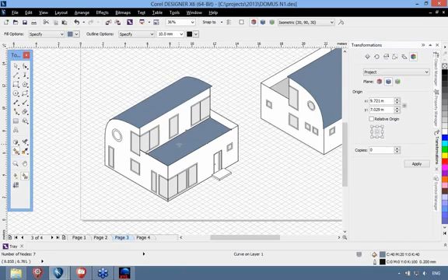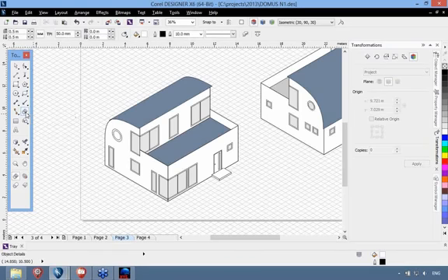Now, let me show you a few of the Corel Designer X6 new features, because that is something you could do with the previous version as well. What is new in X6 is tools for creating projected shapes. So by now, creating a thread or a well would have been quite complex. You could have used one of the symbols that shows a thread or a well in a certain setting. But now you have tools for creating those the way you want. So with the threads and wells, you have options for specifying radius and length, of course, the pitch, and all settings can be specified in a precise way.